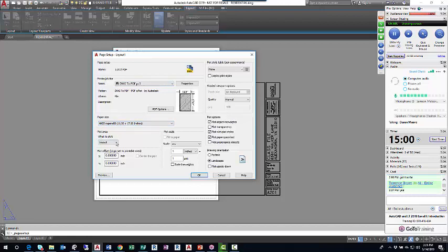I'm going to choose my plot area. Layout is everything here in layout 1. I don't want that. I want extents. I'm going to open up extents, and the border equals the extents now. When you bring anything into a blank environment, and layout 1 was kind of blank, whatever that thing is, it redefines the extents, and that's the border. So I'll left click extents.